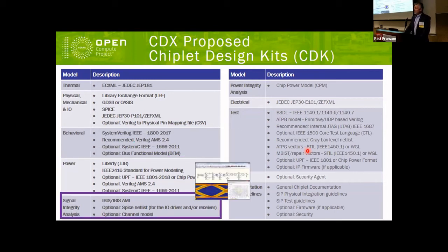So signal integrity analysis is really targeted for the high-speed die-to-die interfaces between the chiplets. The IBIS or SPICE models are requested from the chiplet providers for each of the high-speed die-to-die interfaces for the transceivers. Now, the actual channel in a 2.5D device is routed through the interposer. So when doing a SIP level signal integrity analysis, you'll have to do the extractions on that channel and then use the IBIS models for the chiplet interfaces, and then put those together to form a SPICE level simulation to look at the signal integrity.